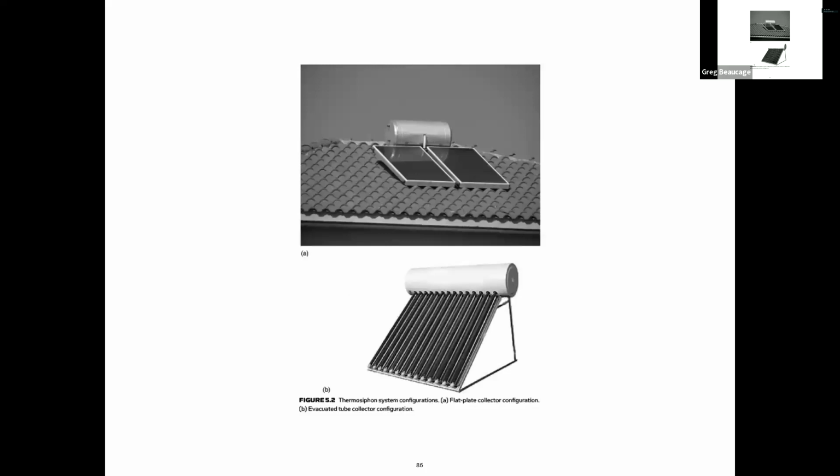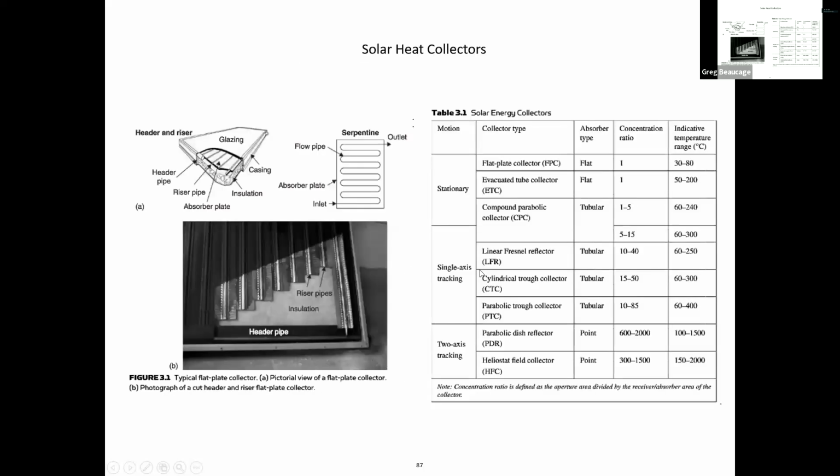These are more commercial solar water heaters, feeding through evacuated tubes like Patrick Sherwin was talking about. You have a tube painted black in the middle, with a vacuum, totally insulated, then the water runs through it. That's one option.